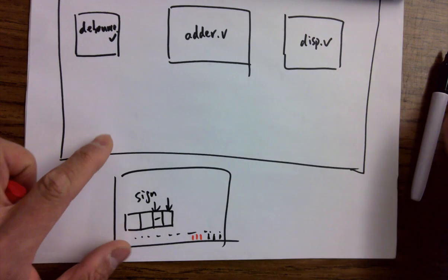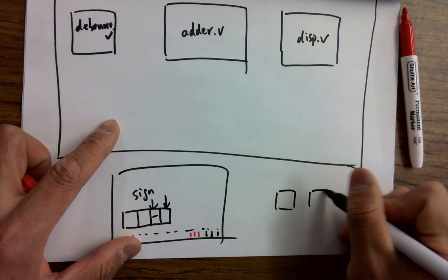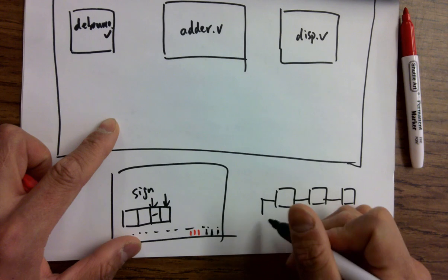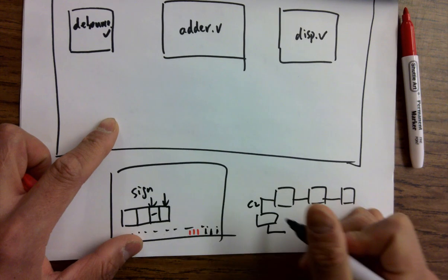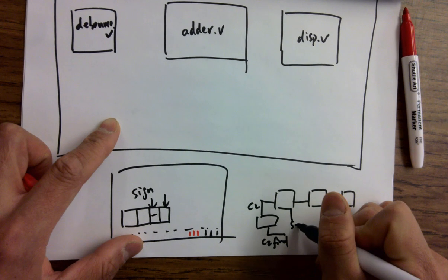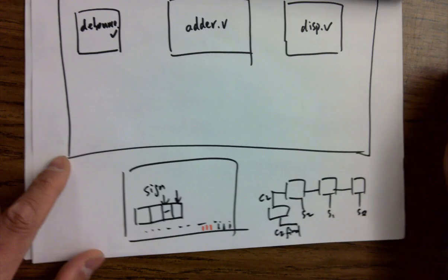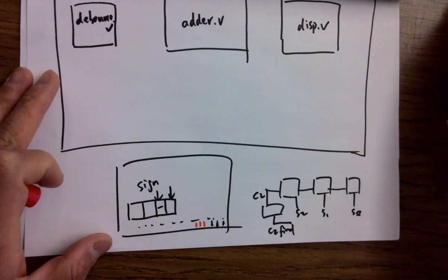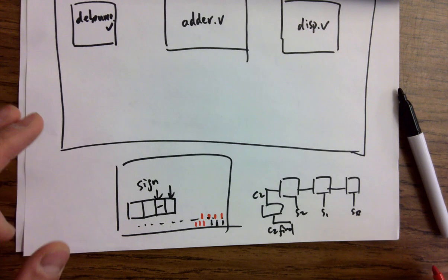And so for the final result, remember we have the full adder. I'm not drawing the details, but you have the full adder, 3 bits. And the C2 is being processed, eventually giving you a C final, C2 final. And here's S2, here's S1, here's S0. So you can see the final result is actually 4 bits. So you need 4 LEDs. 1, 2, 3, 4. 4 LEDs.